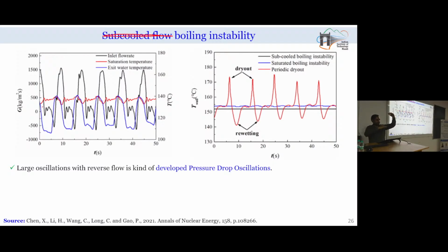Once it is closing the entire portion of the tube, the pressure on the vapor side or outlet side of the heater will become larger in comparison to the pressure at the inlet side, and in this scenario I will be finding some sort of reverse flow. So, here you can see when a significant amount of vapor starts forming, then we get the reverse flow. So, instead of moving water in the forward direction, water will also start coming in the backward direction. Okay. And what is the consequence? The consequence you can see, whenever vapor is forming at the heater surface, you are supplying continuously electric heating or any other type of heating, but vapor is not able to take the heat.